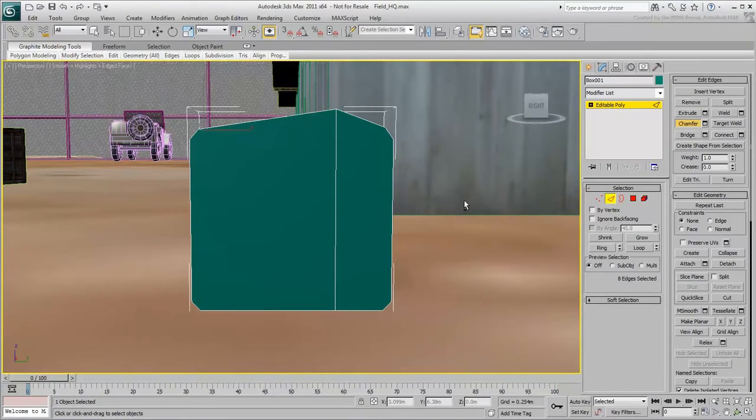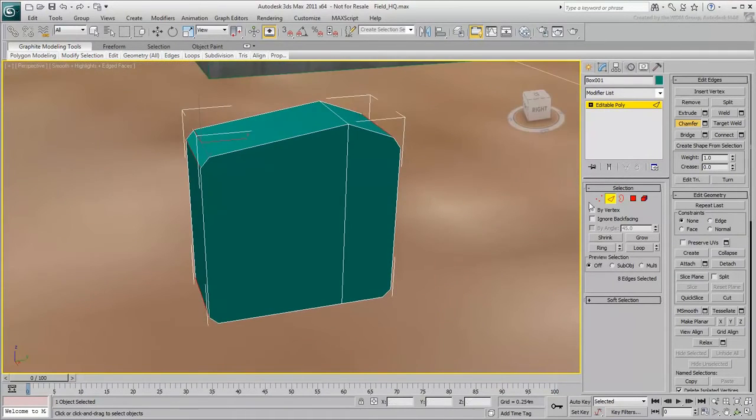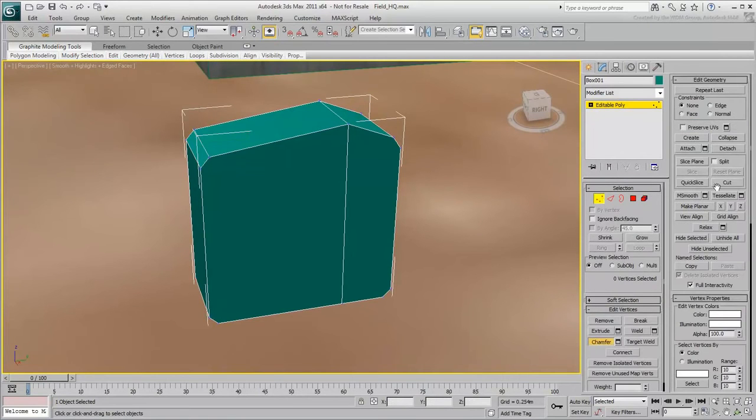6 is an even number, so you can divide each 6-sided polygon to obtain quads. Select the vertex sub-object level. Turn on Cut mode. Place the mouse directly over this vertex. Make sure the correct mouse icon displays, and click to mark that vertex as the start of the cut. Next, place the mouse directly over this vertex, and click again to create the cut. Finally, right-click once to finish the cut. Cut 3 more times so that all the polygons are quads.